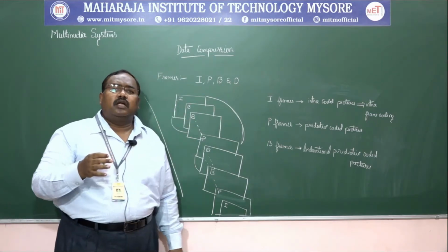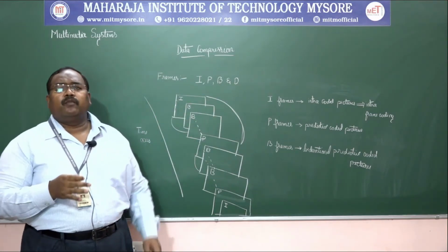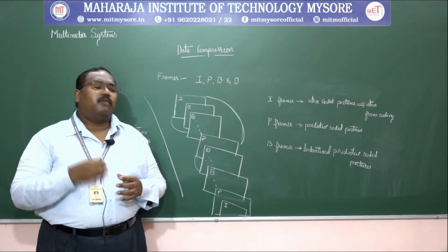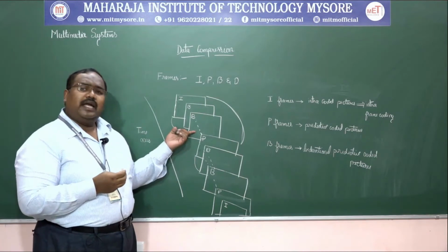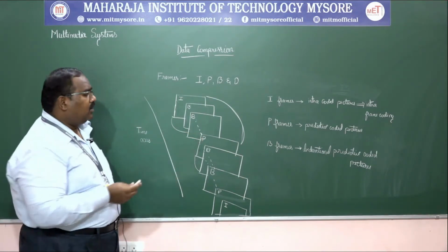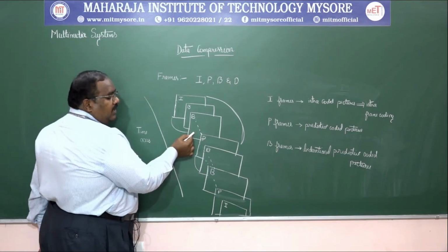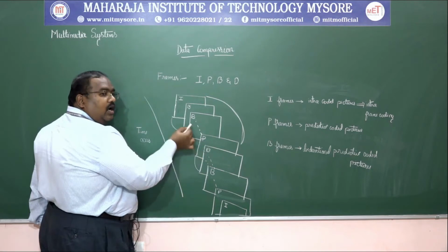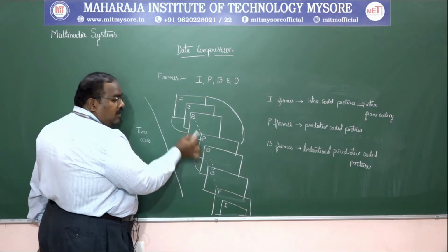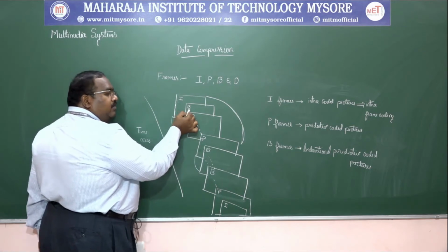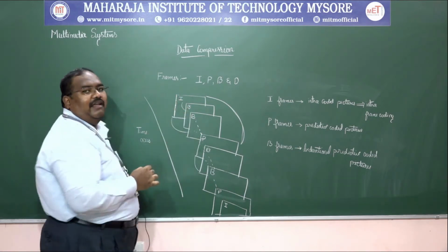So this is called a bidirectional activity. It can be followed by an I-frame or a P-frame. So it can be associated with either a B-frame or a P-frame. So both things can be looked at here. See here, a B-frame is followed by a P-frame in the future, whereas in this case it is being followed by an I-frame.